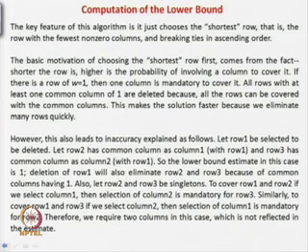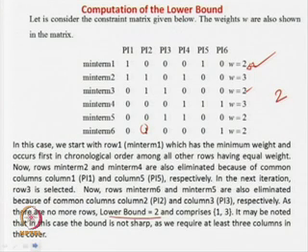Okay, and then we will see what we have done, and again we will come back and explain. So, what is the motivation? The motivation says why we have given our weights. So, we said that the minimum weight is 2 or the minimum weight is 1. That means this row will be covered by the minimum number of columns. It is more difficult to get this included compared to this one, because this row 2 is covered by 3 prime implicants.